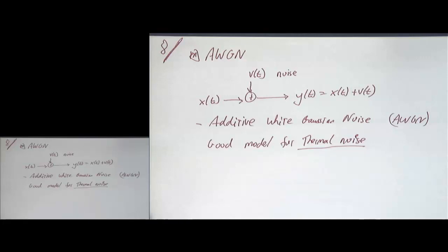But at the receiver, the signal level is so small that that little bit of noise impairment from electrons moving around causes a huge amount of errors in the communication system. So primarily, when we talk about Gaussian noise, we're talking about the noise added at the receiver. This noise is added in every component, but it's normally the noise right at the front end that is the most important. So essentially that's it.